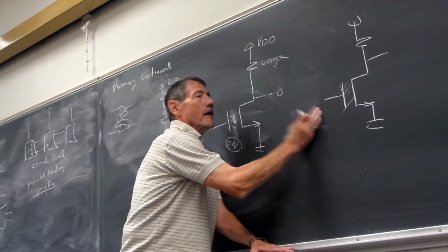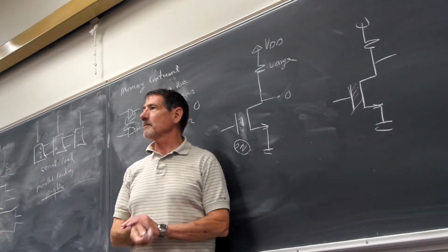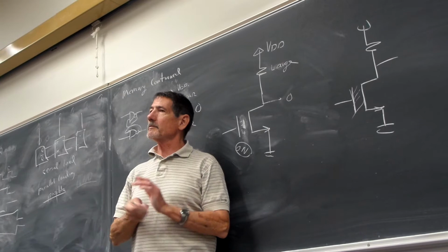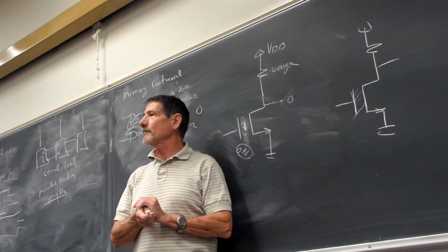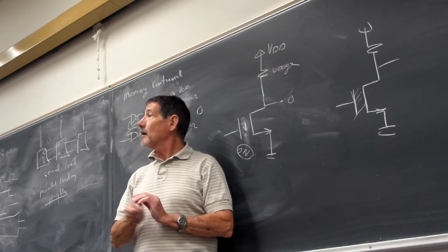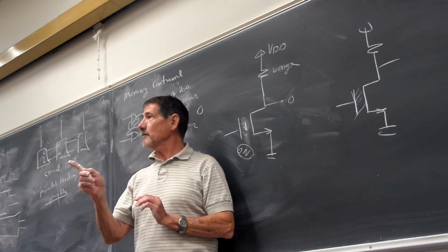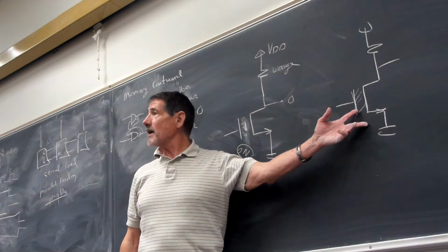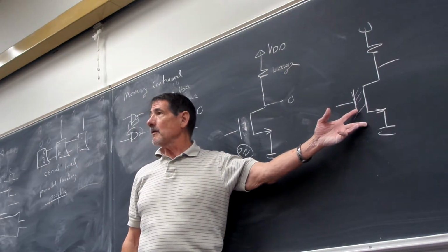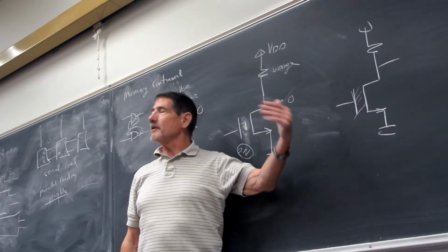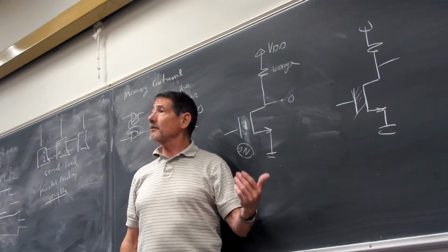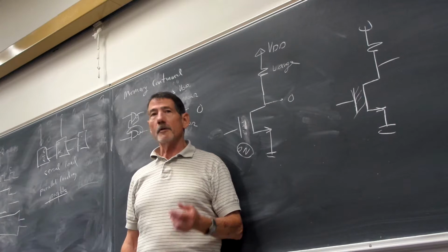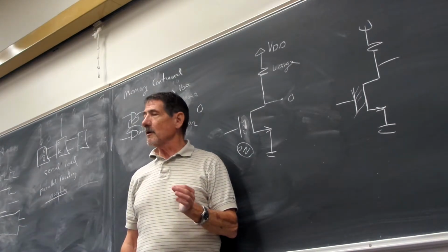Now, I'm going to take that away. No more 5 volts. Is the device on or off? Immediately it's still on. Why is it still on? Because it needs to discharge. You charged the capacitor up, right? But you leave it there, and you leave it there, and you leave it there, what's that charge going to do? Dissipate. It's going to discharge, all right?